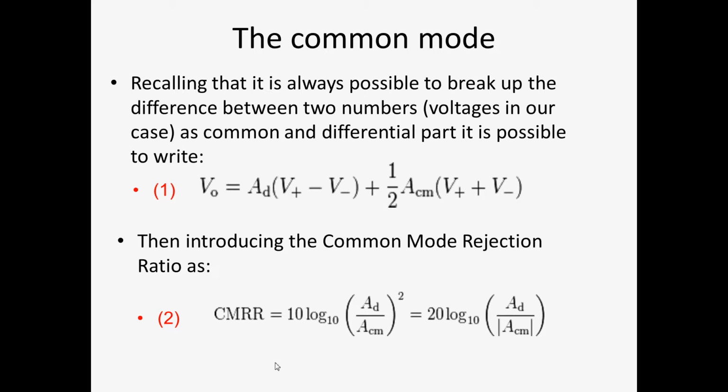This is the reason why you can't appreciate sometimes in physiological recording very small measurements. Because if those small measurements touch the boundaries of your common mode rejection ratio, you are not sure if that is an artifact of the amplifier or actual measurements. An example: EEG, evoked potential.